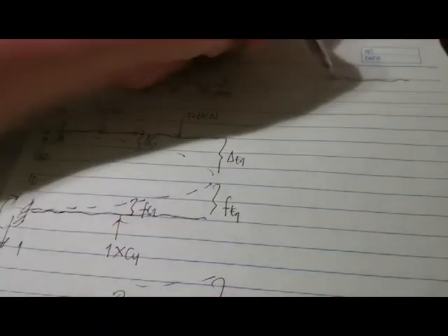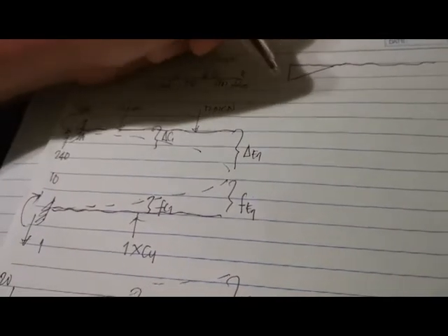So we have a moment due to the concentrated load at point B. So this is 120, so 120 multiplied by 5, 600, but this is causing downward bending, so this will become negative 600.